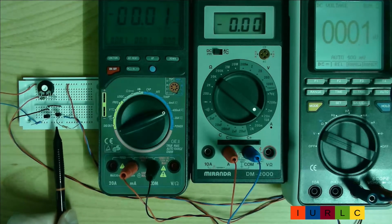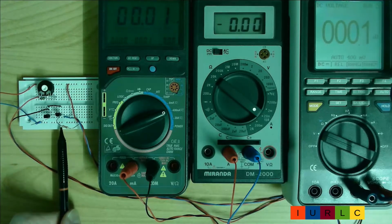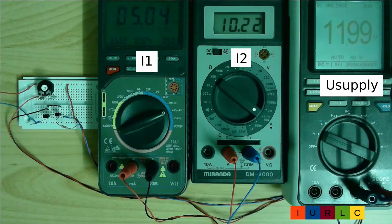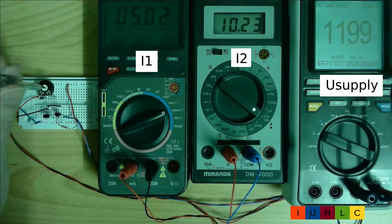Here the 200 ohm emitter resistor of T2 is replaced by a 100 ohm resistor. Measurement 3. We now have a ratio of I1 to I2 of 2. And I start with 5 mA and reduce the current down to 1 mA.